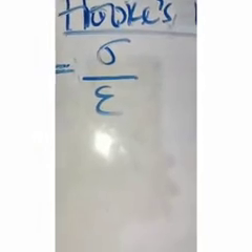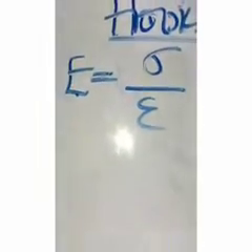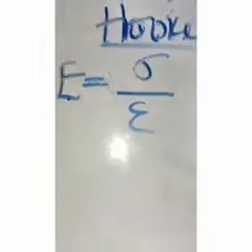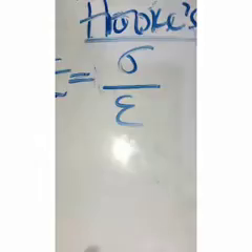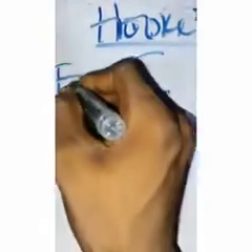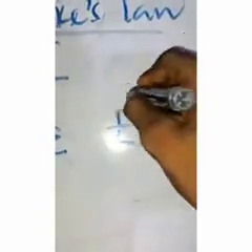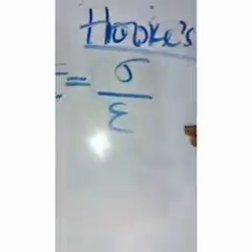So now Young modulus can be defined. This is E. I state Hooke's law again: for a material subjected to simple tension or compression within elastic limits, the stress is proportional to the strain, like you see here, and this is just a constant. So the stress is proportional to the strain, whereby E is the constant of proportionality. So this constant E is now the Young modulus of elasticity and is denoted by E.